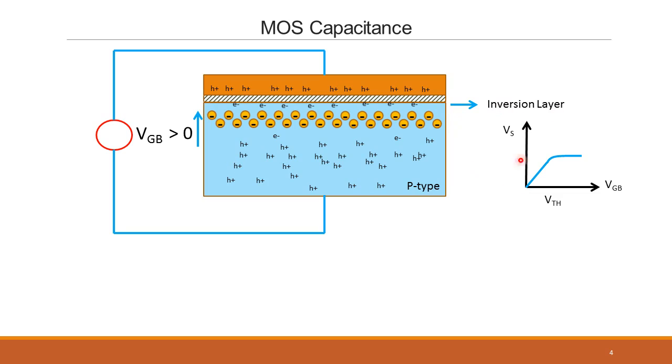And when that happens, the voltage tends to remain constant after that, because remember, it is an exponential dependence on voltage. So if the voltage tends to remain constant here, the field drop across this keeps increasing. And this voltage where the inversion occurs, where the electron starts to become the majority carrier, is called the threshold voltage. So beyond the threshold voltage, the voltage at this point doesn't change too much in the inversion region.